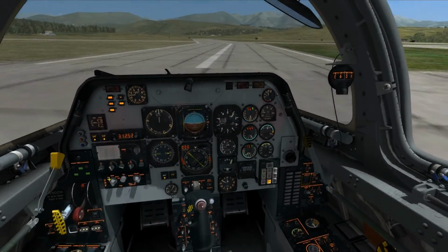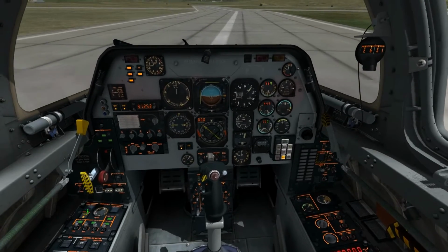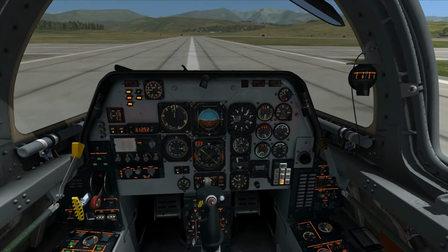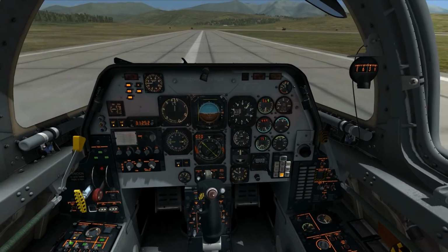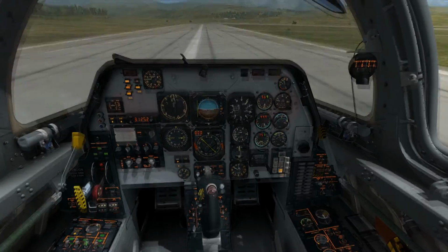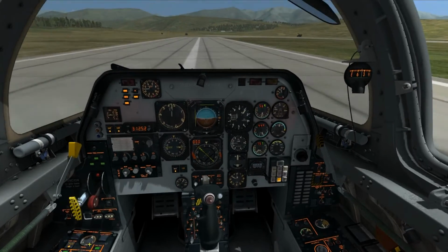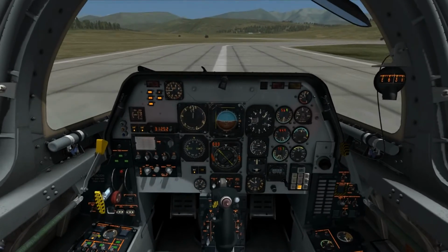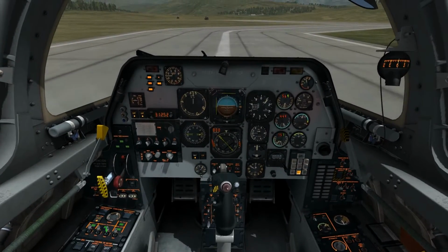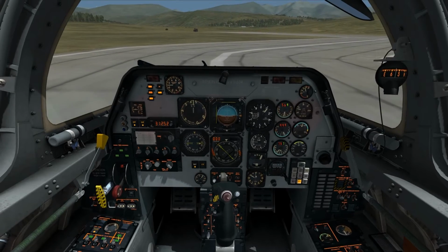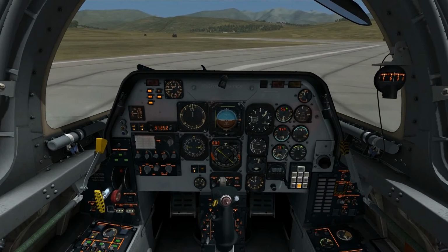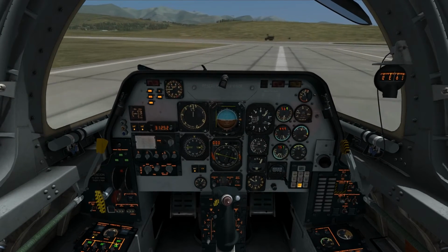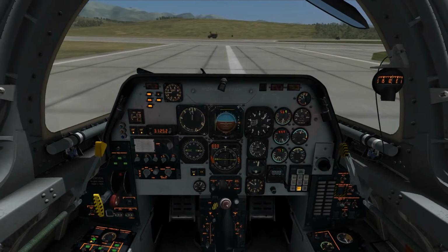The question of the fuel system is that we have a main fuselage tank, and the other 3 tanks are passing their fuel to the main fuselage tank. These 3 tanks are one in the left wing, on the right wing, and on the center section of the wing. Each one has at least one fuel pump. This pump does not pump fuel into the engine, but in the fuselage tank. The center has 2 pumps. This green light indicates that the fuel is passing from these 3 tanks to the main fuselage tank.